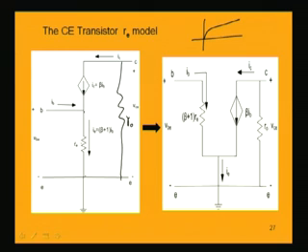Now, in order to conveniently separate out the input and output circuits for further convenience in analysis, one trick we can do here is that we can represent this resistance in another way. If we consider the voltage drop between these two points B and E, what is this voltage drop? VBE is equal to RE into IE, that is RE into (beta plus 1) IB. So, if we keep IB and keep this together, what do I get? RE into (beta plus 1), but the current can be expressed by the same current IB flowing through this resistance, but the resistance value will be different now, it will be (beta plus 1) into RE.